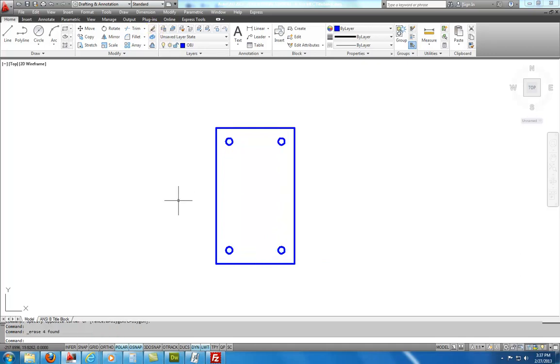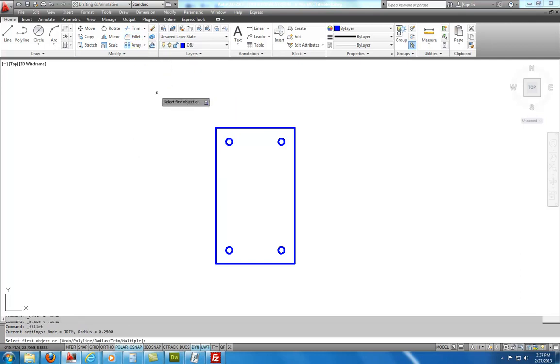Next thing I'm going to do is I'm going to fillet these edges here, and the fillet is also 0.5, but it's a 0.5 radius, and so you have to differentiate between diameters and radius when you do these drawings. I'm going to select the fillet command. If you don't see the fillet, it might be buried under here, and so the last command is on the top. And you'll also notice that there's this little down arrow, and if you hit the down arrow on the keyboard, it allows me to select radius, and the down arrow I'm talking about is this right here. And those are your options.